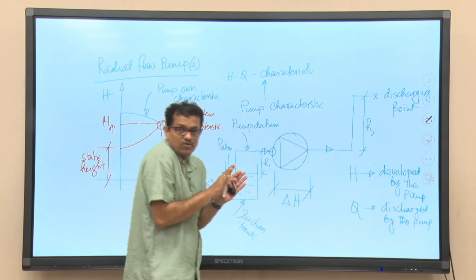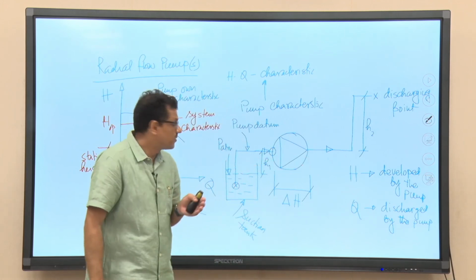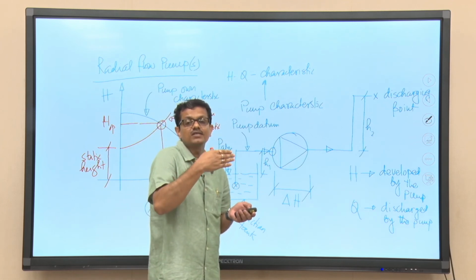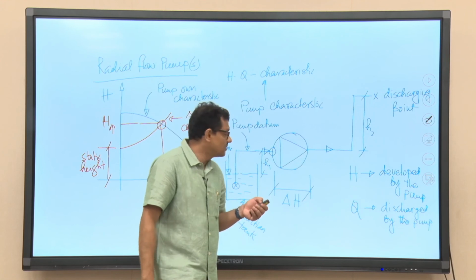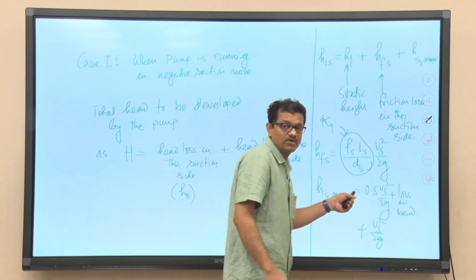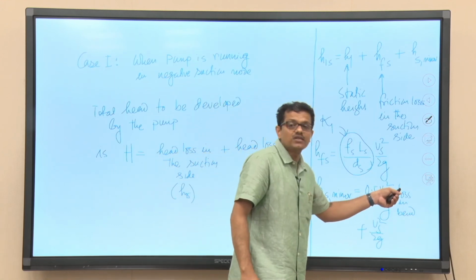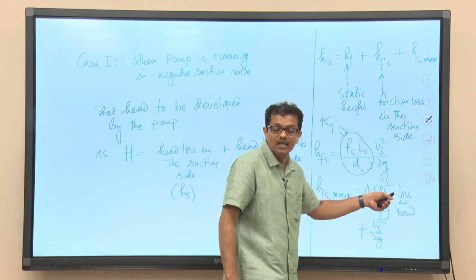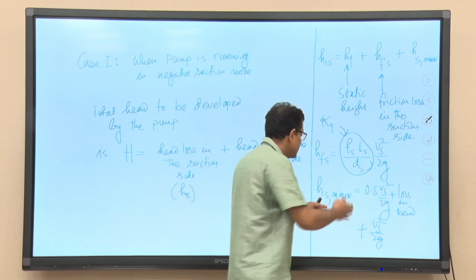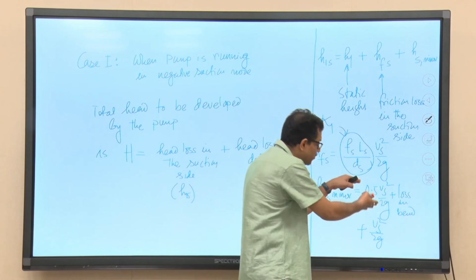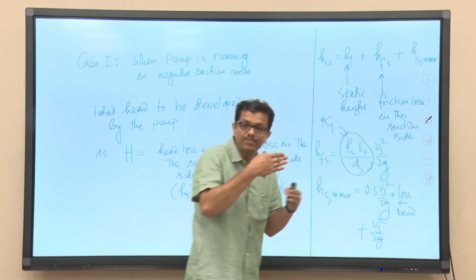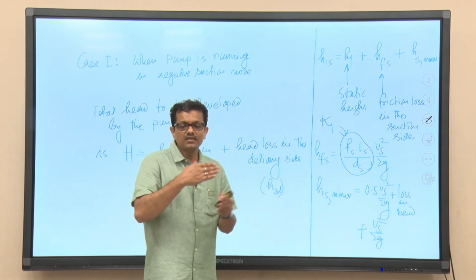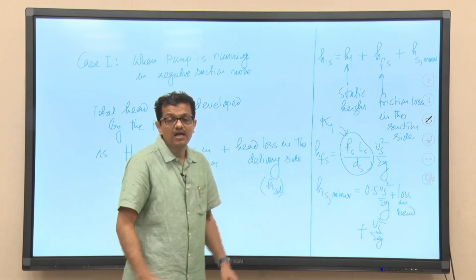So, there will not be any mistake in that calculation, but the mistake will be there while calculating the friction loss and the minor losses. What is most important is the minor losses, because you really do not know the loss in the bend, that is why I could not write the mathematical expression. What is done in practice normally, instead of calculating the minor losses following this equation, is that it is taken as a percentage of the total losses to keep the system in a safe mode.